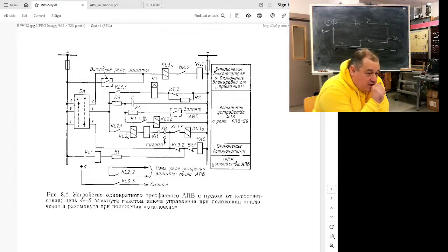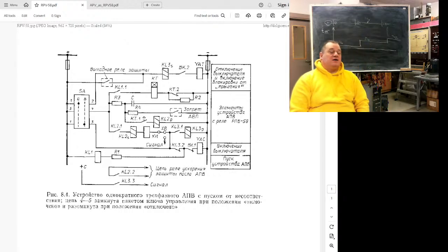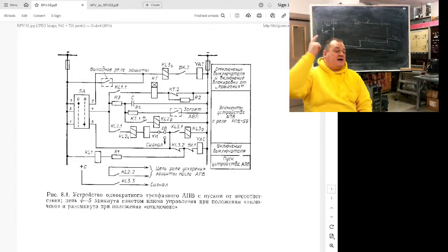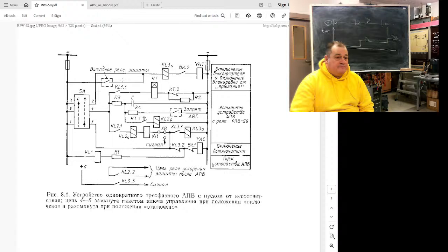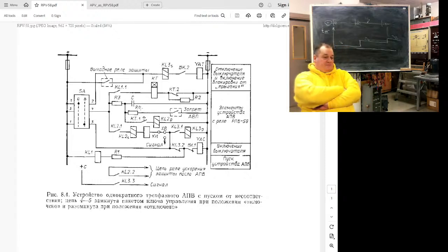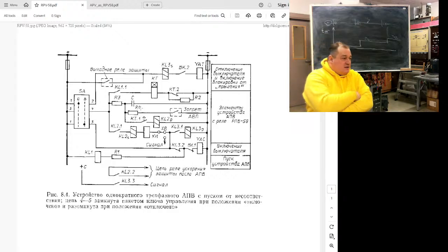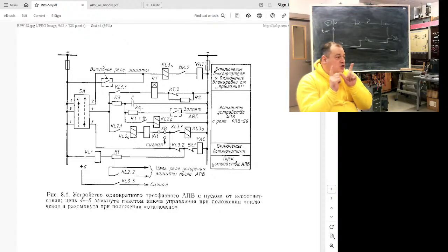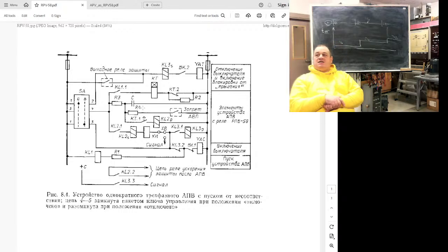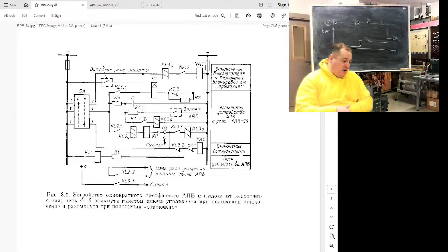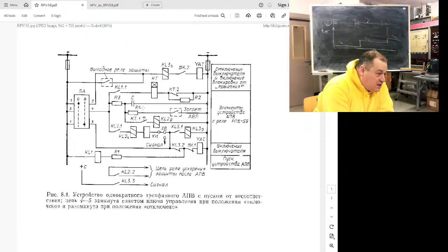At the first operation of auto reclosing, the capacitor will be charged. And what will happen when we had disconnect, connect, but we have switch on fault? Again, a disconnection command should trigger auto reclosing, but the capacitor is not charged. This RC circuit is a very basic timer. It says that auto reclosing is possible only with some time delay; the switch should remain on until this capacitor charges. Actually, it's a single action. This basic timer ensures single action. There will be no second auto reclosing.